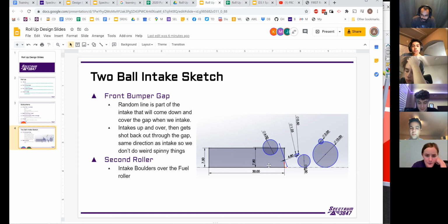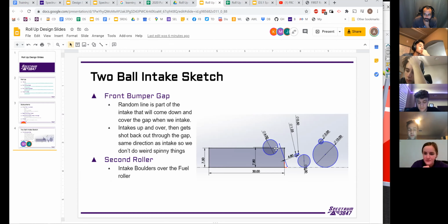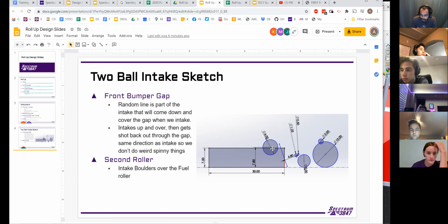One could be coming out below, one could be coming out above. There's ways to have different mechanisms do the firing and them still going in roughly a straight line. Oh yeah, you could have intakes from different locations, but they both go toward the same shooter direction. In this version, what we were discussing, the small balls would come out from underneath when fired, and the big balls would come out the same intake path, so they'd be in the same straight line, and the same side of the robot and everything. Which makes things a little bit easier on weight because everything's built into the same spot, but it's a little complex because everything's built into the same spot.